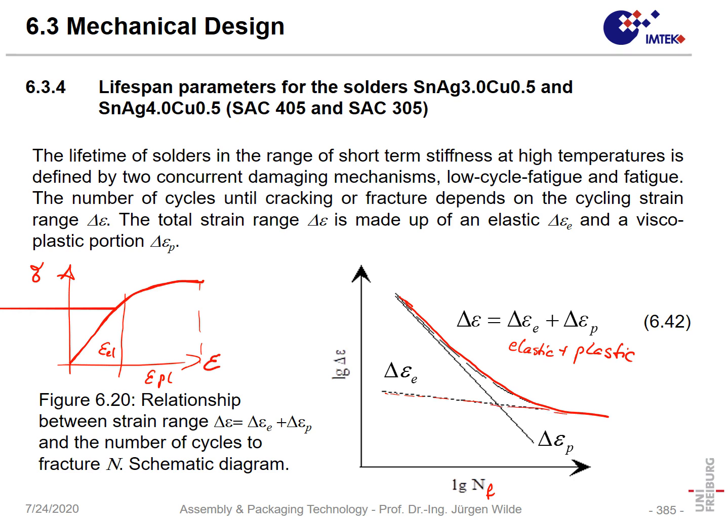So that's a normal fatigue curve, and that curve here is the low cycle fatigue curve, which is dependent on plastic strain, and that is relevant for solder joints. So the elastic deformation in solder joints is not very high, but the plastic deformation is what decides the lifetime here.